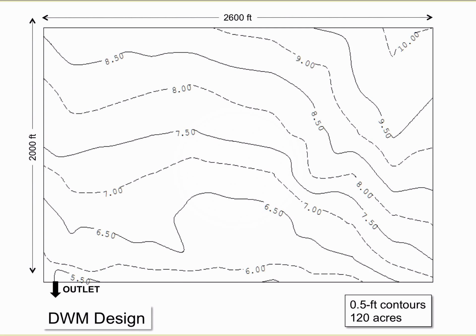So let me start then with looking at, what do I want to do here? A 2-foot contour. No, I'm going to do a 1.5-foot contour. Since I'm designing the system, I'd like to cut back on that elevation interval, get a little higher degree of water table control. So I'm going to start at the 5.5 elevation and go to 7 feet for my first zone. And I'm going to sketch that out here in blue. I'll go from 5.5 feet to 7.